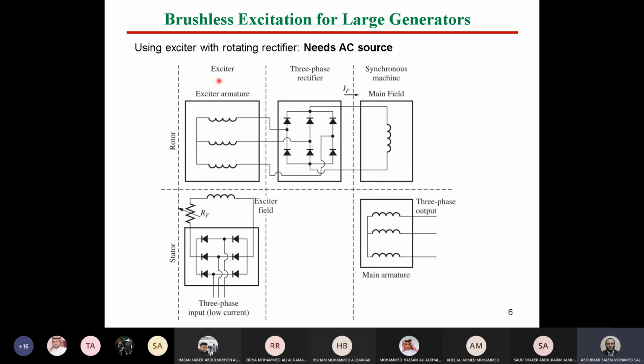However, the exciter machine is a bit different compared to a DC machine. What is the difference? In DC motors or generators, we have a part called the commutator. This commutator is a cylinder made of, for simplicity, just 2 half cylinders, connected to brushes in order to convert AC to DC. This is the main purpose of the commutator in DC machines.